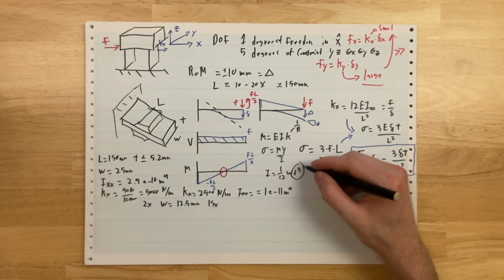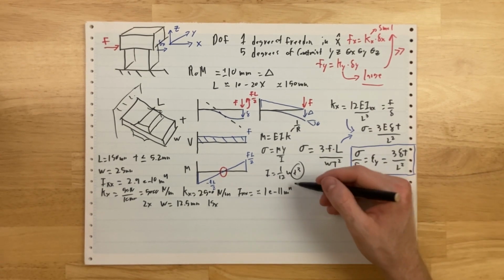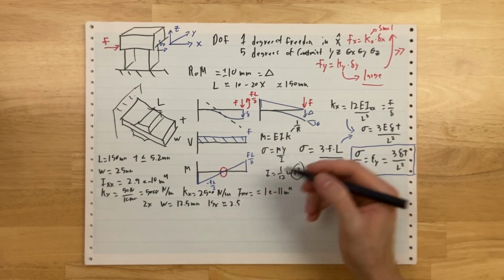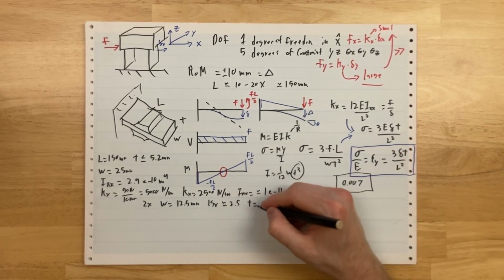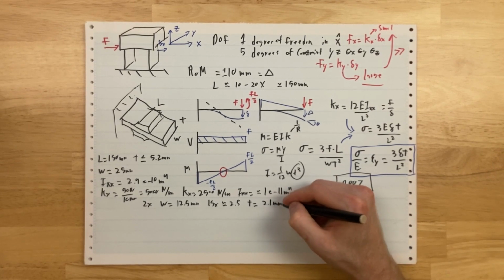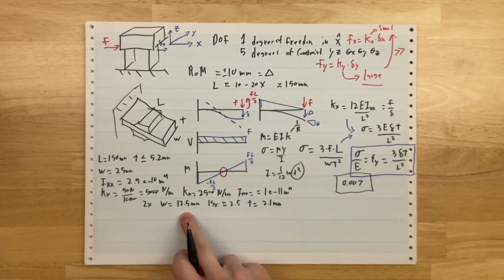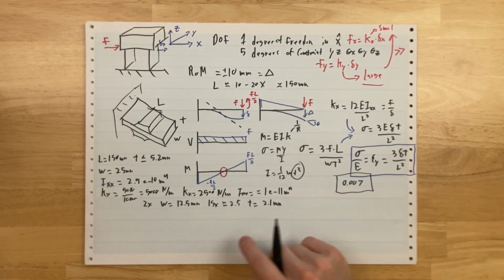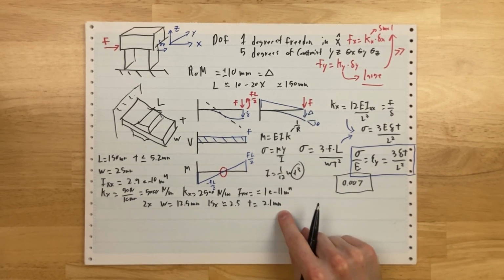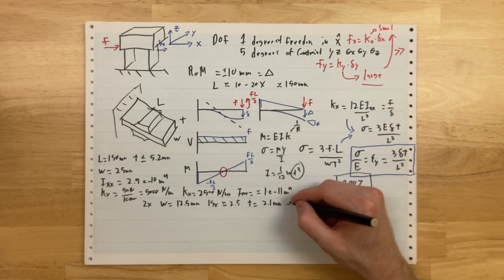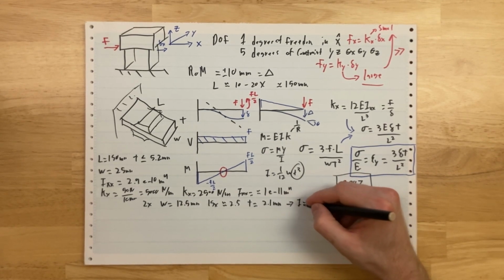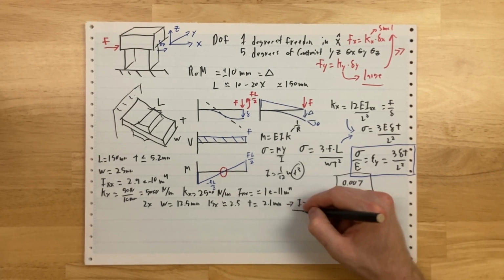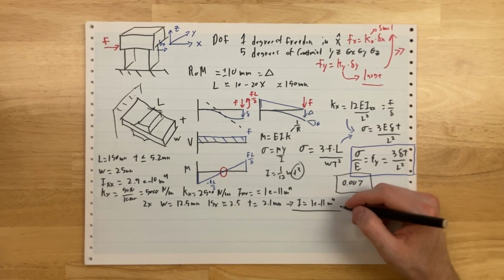So if I want T cubed to change by 15x, the cube root of 15 is about 2.5. Putting that together, I just need to drop my thickness down to 2.1 millimeters and my width down to 12.5, and now I have reduced the I by a factor of 30. My T is still less than 5.2, so I'm fine on the stress criteria. Now when I plug this together, I get an I, again, of about 1E-11 meters to the fourth. So now I'm good to go on the stiffness criteria.